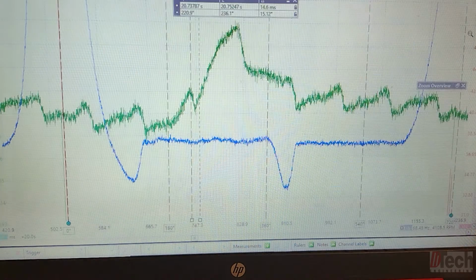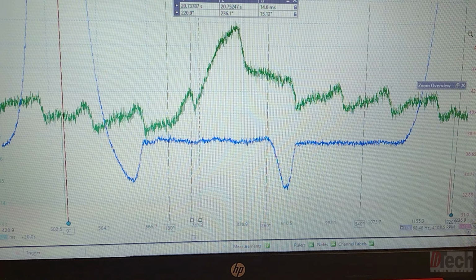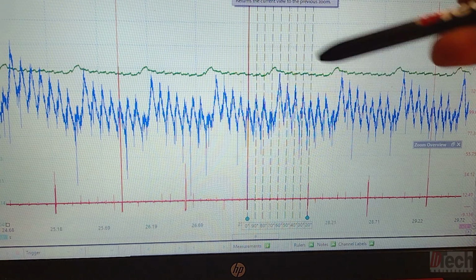And again, the intake pulse waveform gives us the final dagger of what's mechanically going on by aiding with the relative compression low cylinder number 8. It shows us that the pressure loss for 8 is bleeding off into the intake manifold, and that is our issue.